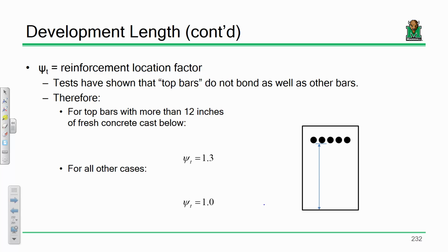Now, if you don't consolidate that cylinder well enough, if you don't rod it or give it the old tap on the side, what happens to the cylinder? What do you get in the cylinder? Voids, right? Okay, so not only do you get voids, let me also ask you this. Where are you more likely to get those voids? On the bottom of the cylinder or the top of the cylinder? The top. Why would you be more likely to get voids on the top as opposed to the bottom? Exactly, it's gravity. That concrete is going to want to settle towards the bottom, right?